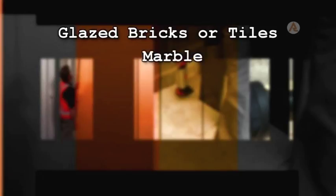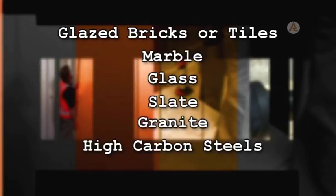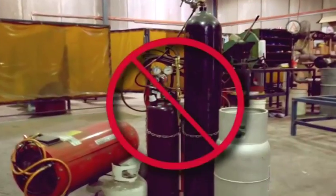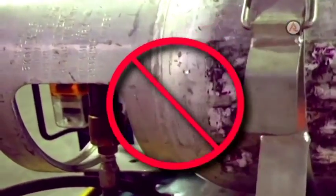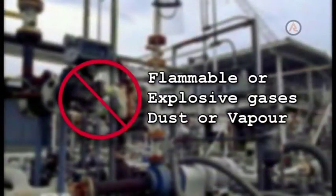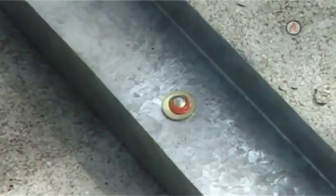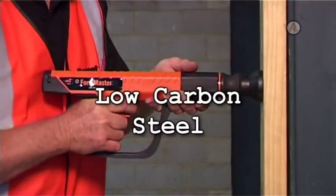Hard or brittle materials such as glazed bricks or tiles, marble, glass, slate, granite or high carbon steels should not have fasteners driven into them by this process, as shattering can occur. Never attempt to fasten onto pressurized vessels such as compressed gas cylinders. The tool must not be used in the presence of flammable or explosive gases, dust or vapor. Common materials that are suitable for powder-actuated fastenings include concrete and low-carbon steel.